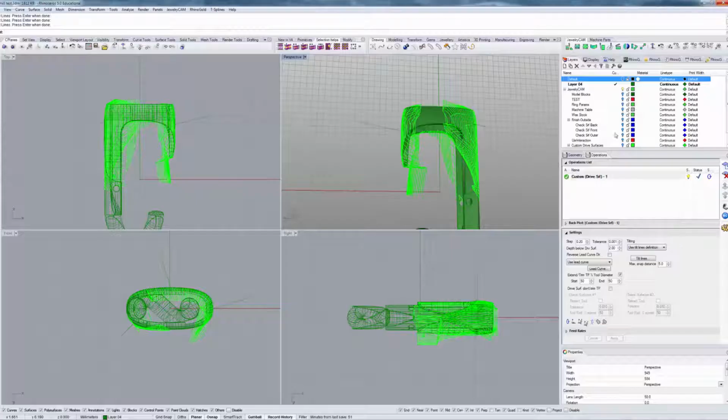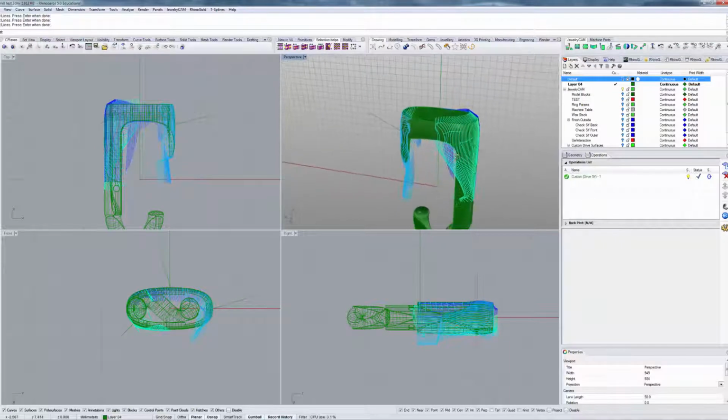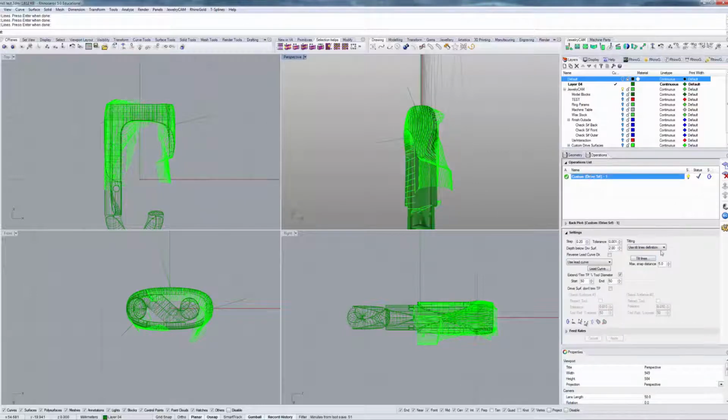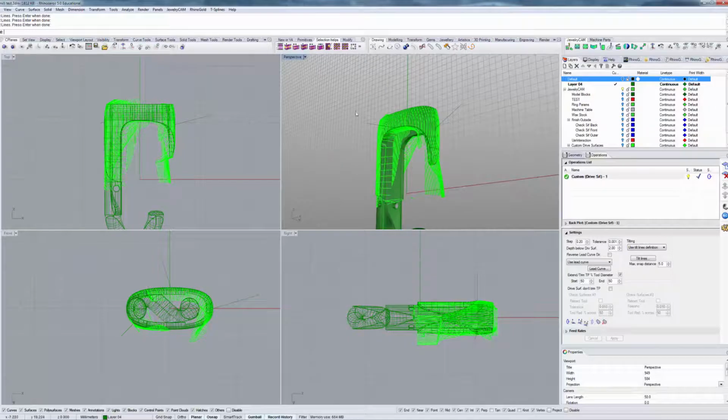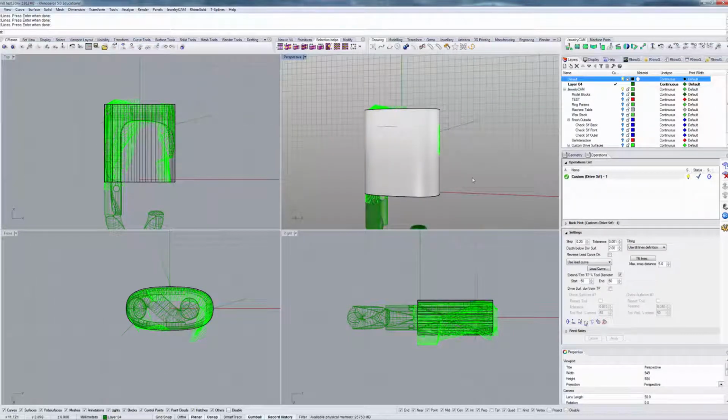You might leave everything else at default. You might create tilt lines that are exactly perpendicular as you would with a default strategy anyways. But then for a certain angle, you might say, well, I want to cut precisely this way. And tilt line definitions allow you to do just that, while still working with the same very basic primitive looking drive surface.